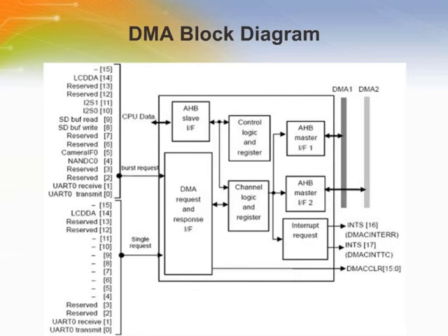Here we show a block diagram of the DMA controller, which has 8 channels and also has a bus master which is 32 bits by 2. Its priority is DMA channel 0 high to DMA channel 7 low, and first in first out of 4 words by 8 channels. It has a bus width of 8, 16, or 32 bits. Its transfer count is approximately 4095. It supports only little endian type.